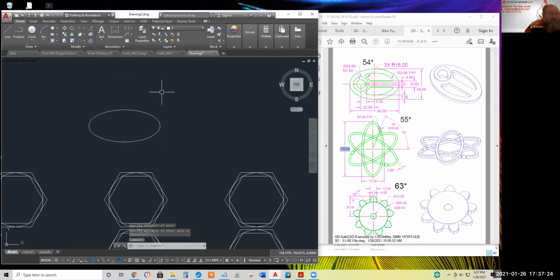Now, I believe if we explode this, it forms into a polyline with a gazillion vertices on it. Very good, rather high file storage. Let's explode it and find out. Hit enter. Now I select it and it's not any different. Interesting. LI for the list command.